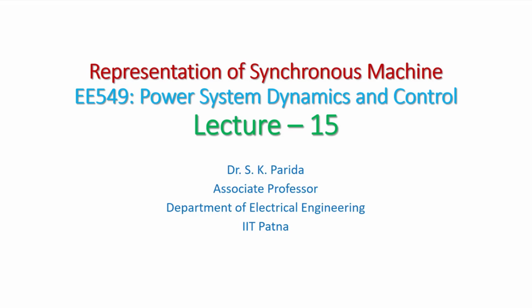So now we'll start looking at how we can represent these machines, because a power system does not consist of one machine. When you did the modeling of the synchronous machine, you saw the DQ transformation. We should remember that this DQ transformation is only in reference to a single machine, that particular machine where you are doing the modeling, right?